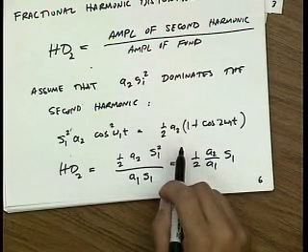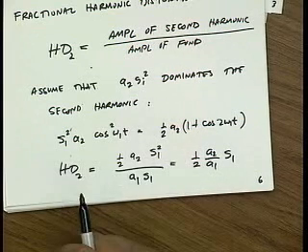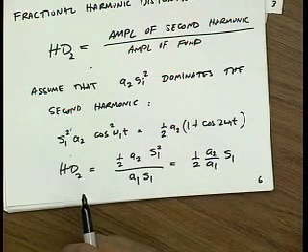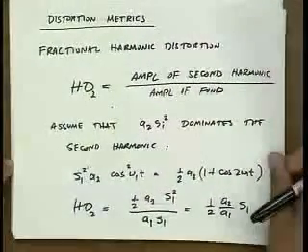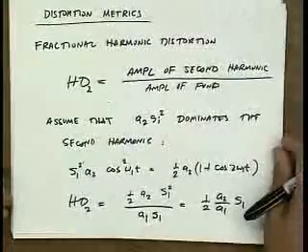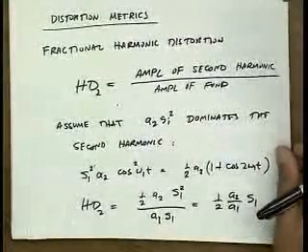And that DC is actually going to compete with your signal. If you have a low IF or zero-IF system, then that DC is going to corrupt your signal. So it is, in fact, very important. But very good question. For those of you who didn't follow, we'll talk more about system-level issues probably today, actually. We'll get to there. Okay.